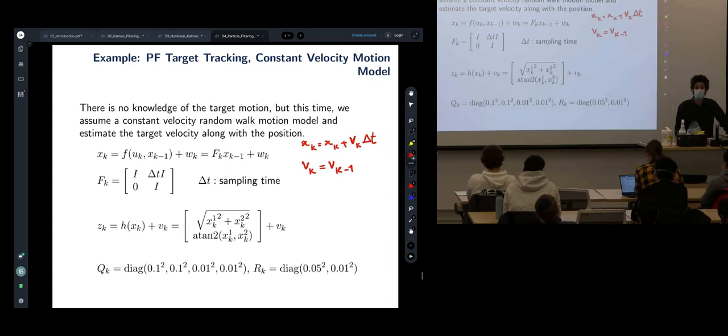Which, if you have an IMU, then you can do that. On the object that is moving, if you can measure it, then the input is the acceleration, and you can include a better model here for velocity integration.